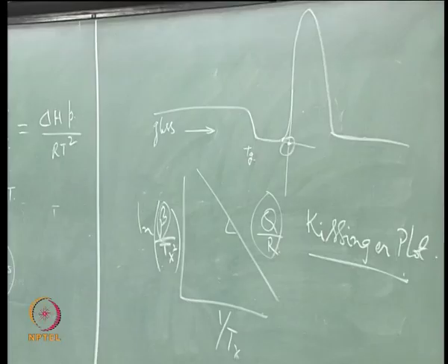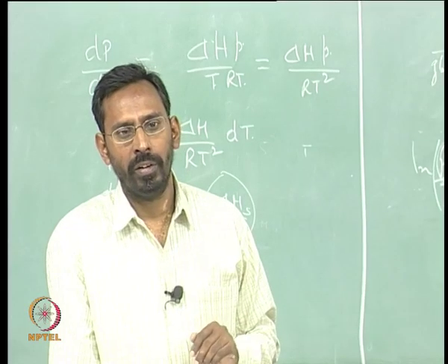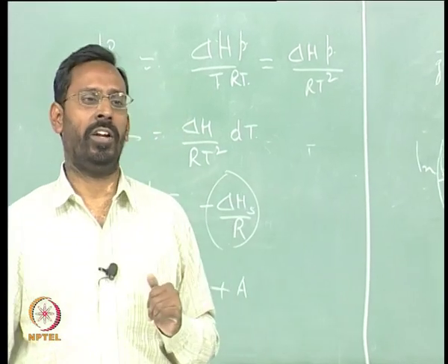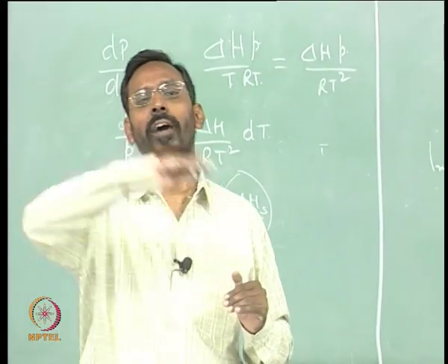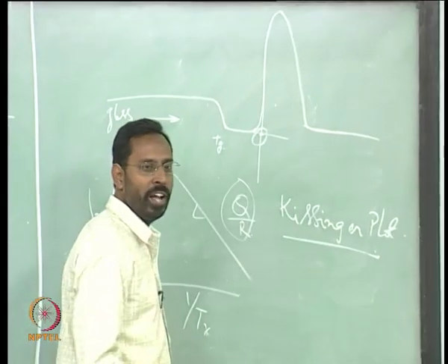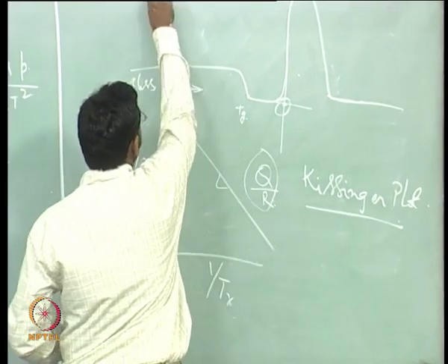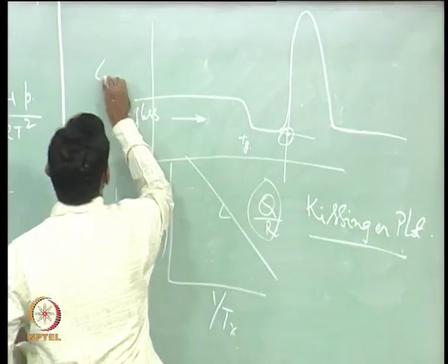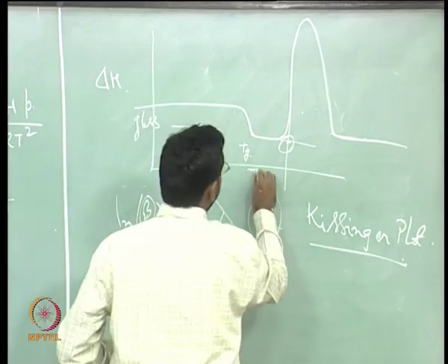What do we mean by athermal kinetics? It means as a function of heating at different rates you are doing it. You can also have what is called isothermal kinetics. That means at a given temperature you try to have the transformation taking place. In principle, if I do the same transformation in a DSC, what we plot is delta H versus temperature.